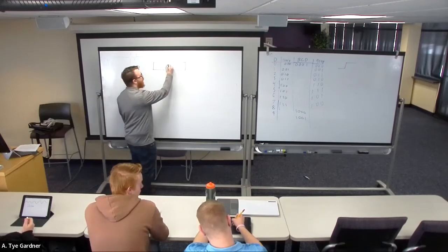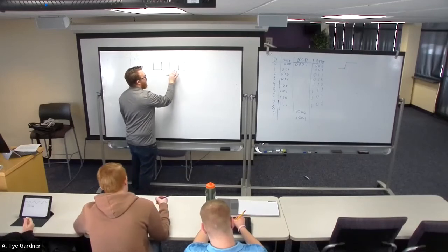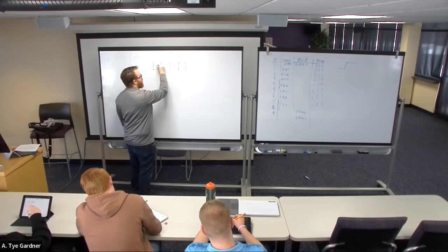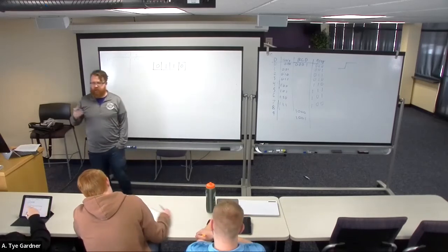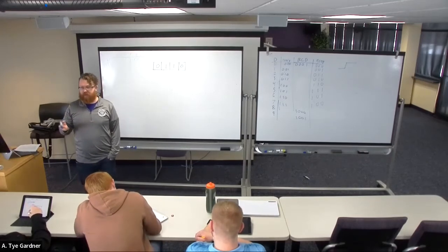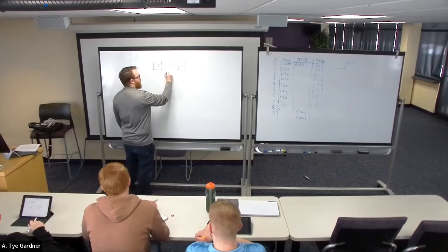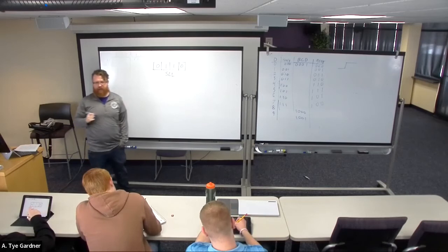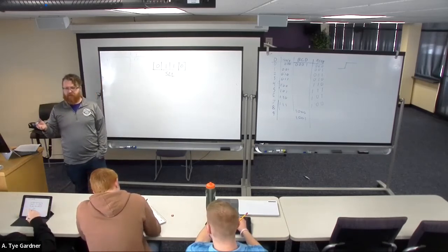Okay? So let's say I have a standard logic vector of 0 1 1 0. What a shifter does is I can shift left or shift right. So if I want to shift left logical, SLL, this will make more sense later, but this is how we reference it in VHDL.